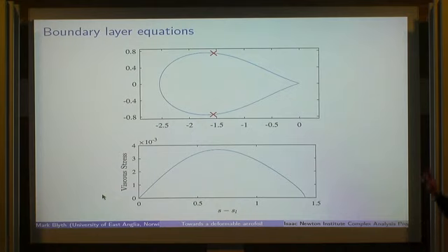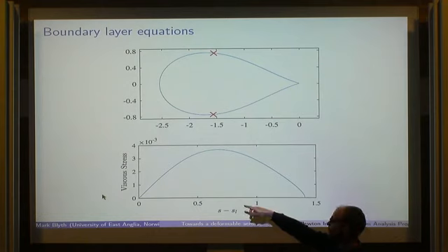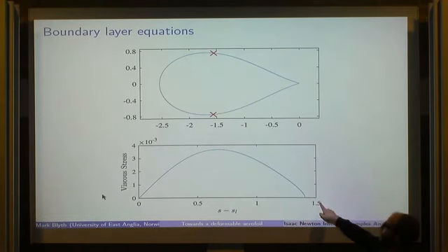So here's a typical example. The big red crosses indicate where separation occurs. This is the viscous stress, du/dy, plotted against distance from the stagnation point. It hits zero here, which corresponds to that red cross. So that cell is going to separate at the top, and there's going to be a big wake, and that means the potential flow solutions I've been talking about are going to be completely irrelevant to the real flow.